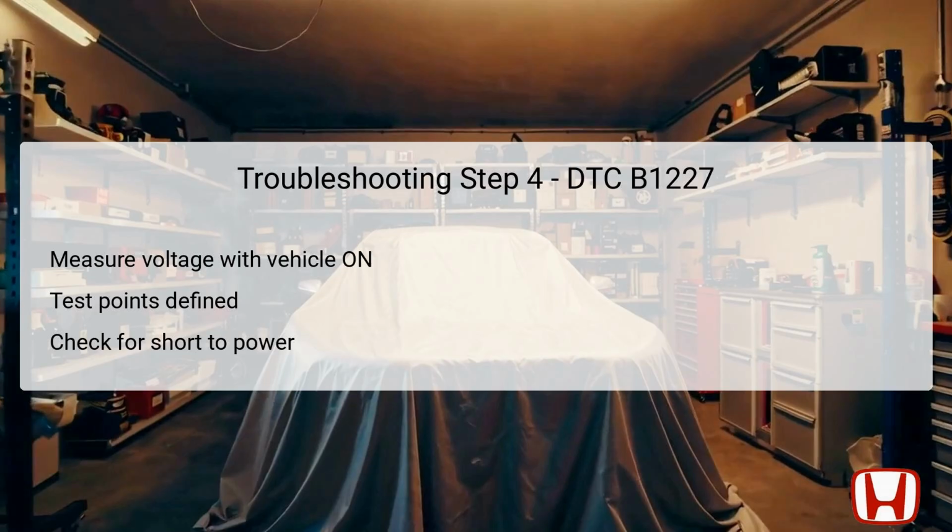This voltage measurement is critical as it identifies whether the TAM wire has shorted to power, which could have resulted in the open circuit issue. If voltage is detected during this check, it confirms that a repair is needed for the short in the TAM wire. If no voltage is evident, this indicates that the TAM wire is likely intact, allowing the troubleshooting to progress further.